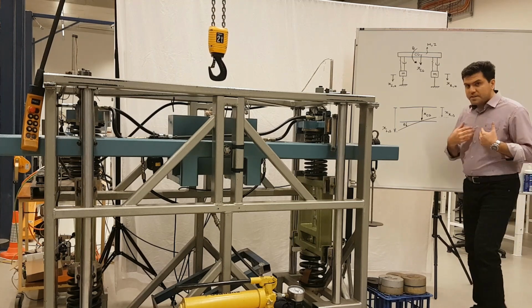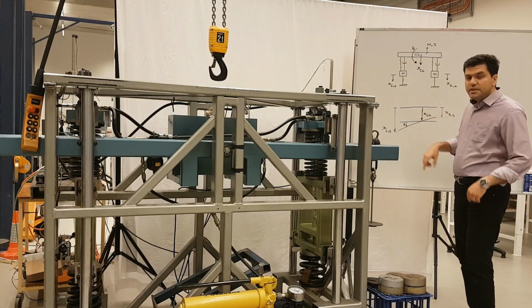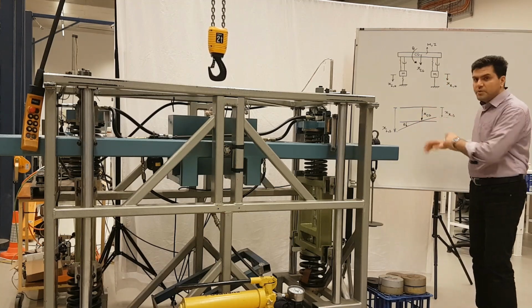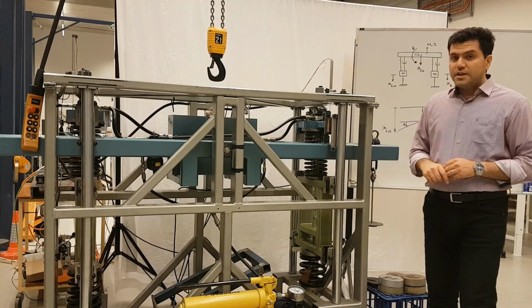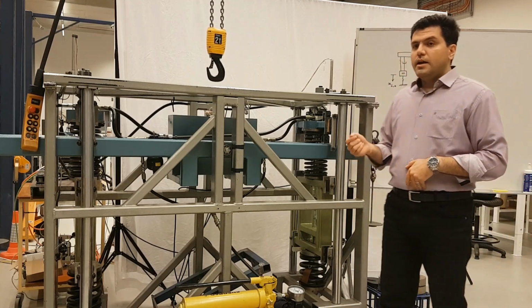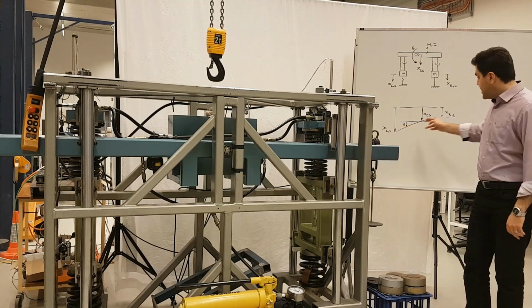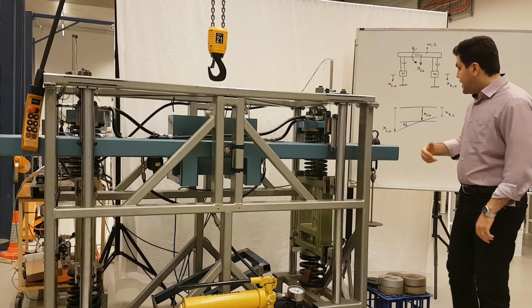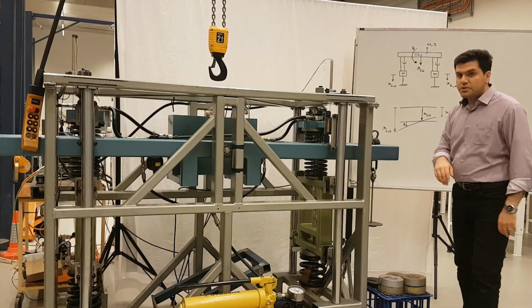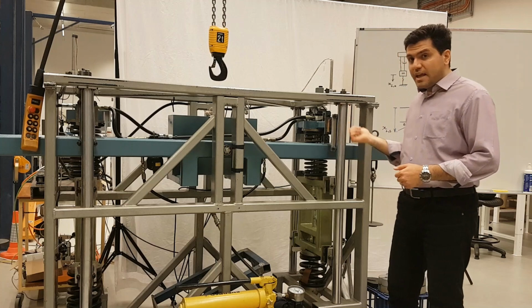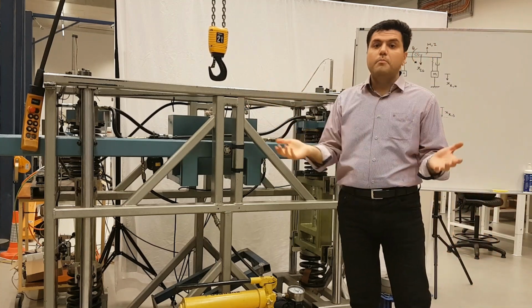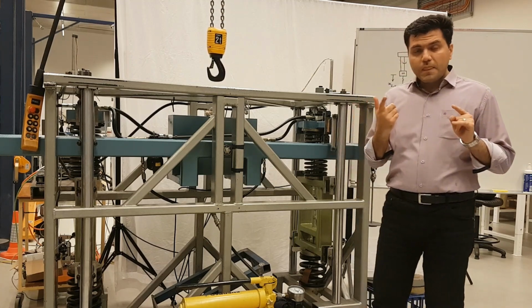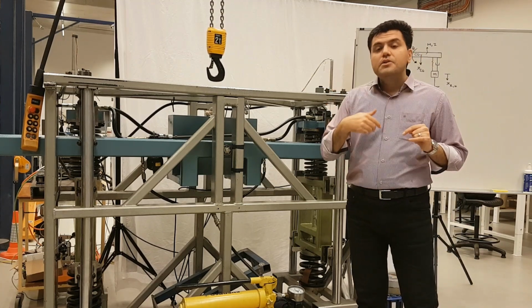So what we're interested in is just to measure XCG, the displacement of center of gravity, and also theta here. By doing some simple calculation, you can find the relationship between XCG and X left sprung mass and X right sprung mass, and also the relationship between theta and X left sprung mass and X right sprung mass. Meaning that X left sprung mass and X right sprung mass are dependent coordinates. So they are dependent on XCG and theta.